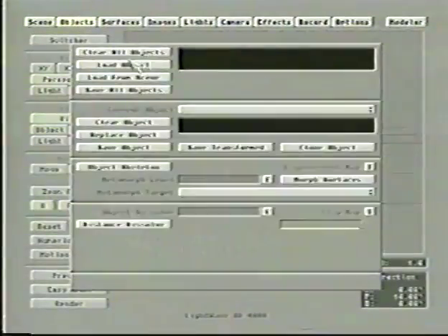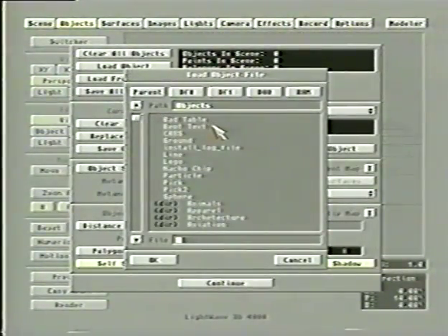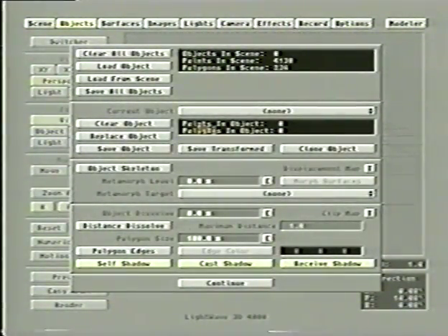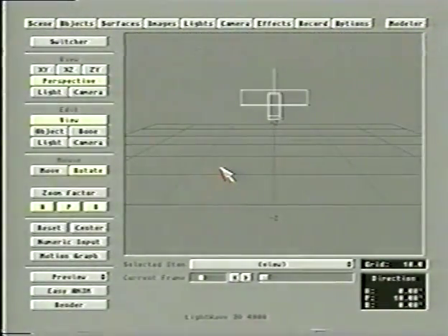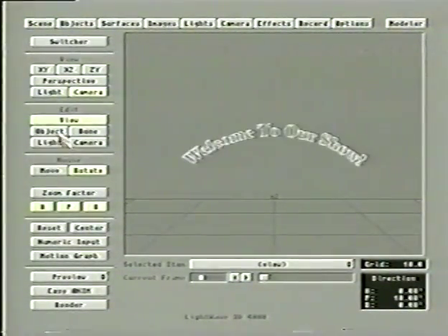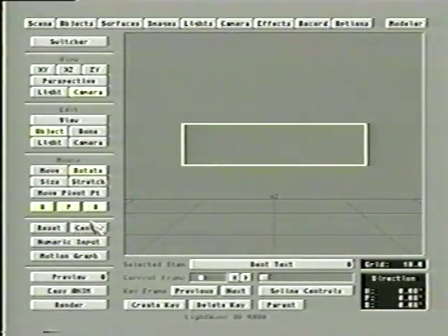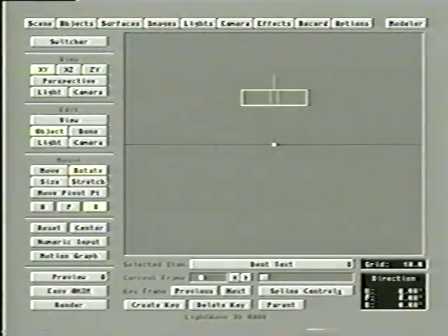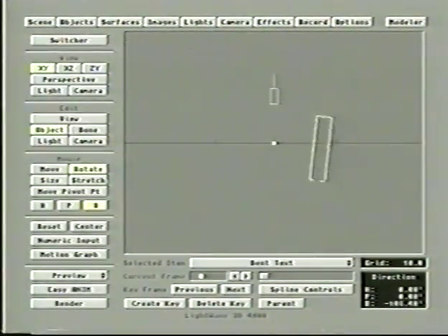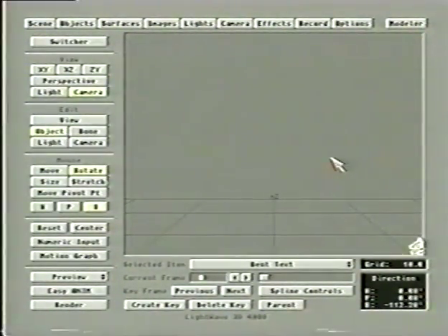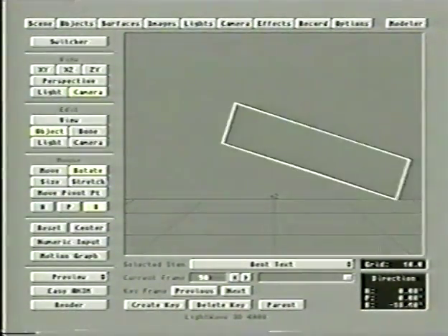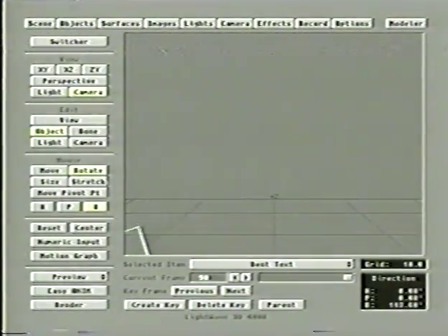All right, now if we load up the object into layout, all we need to do is choose the object, rotate. In this case, we're rotating around bank, so I turn off everything but bank. And what you'll see is it's rotating. Since it's rotating around the pivot point, let's just keyframe it here at 0, then let's say at frame 90. Put it over here.